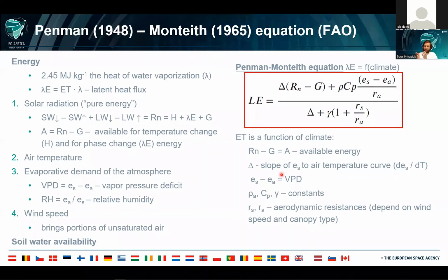So what we got here is the equation where we can compute everything from meteorological data and some knowledge of the surface, but not the knowledge of surface temperature. This approach is now considered the benchmark of the Food and Agriculture Organization. It has been reported in the proceedings of paper 56, FAO 56. I will give a link later at the end of the video. This is the baseline for evapotranspiration estimation.